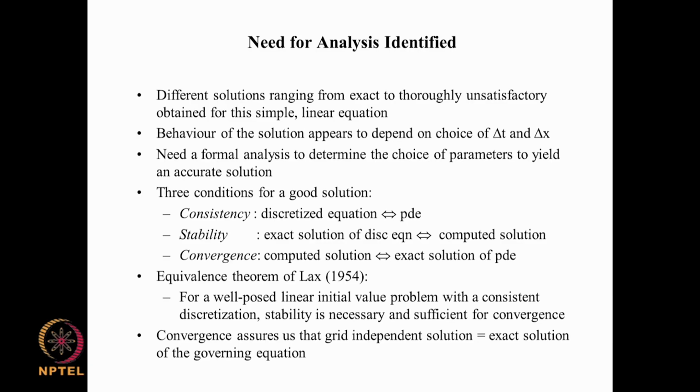So, here when we look at the analysis, we notice that our CFD solution is done in stages. That is, we first convert the partial differential equation to a discretized equation, and then we solve the discretized equation. We do not solve the partial differential equation. So, the solution is obtained in two steps: one is converting the PDE into a discretized algebraic equation, and then solving the set of algebraic equations in order to get a solution.